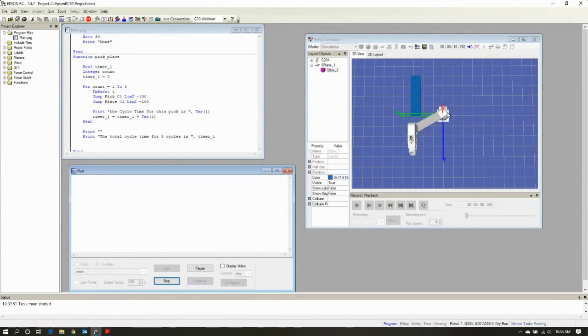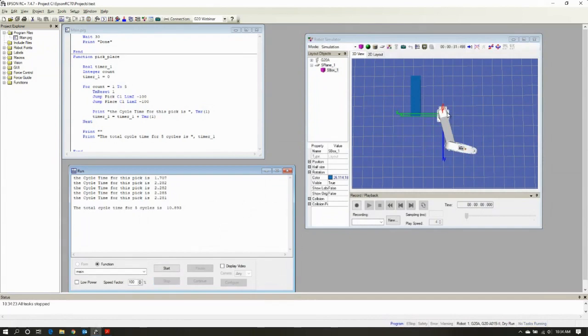The arm itself is in what we would refer to as a righty configuration, meaning from the back of the robot to the front, the elbow is pointing on the right-hand side. If you notice, almost all of the motion that's going on here is all centered around joint 1. Joint 1 is the slowest of the joints because of its gear ratio. Joint 2 is doing nothing.